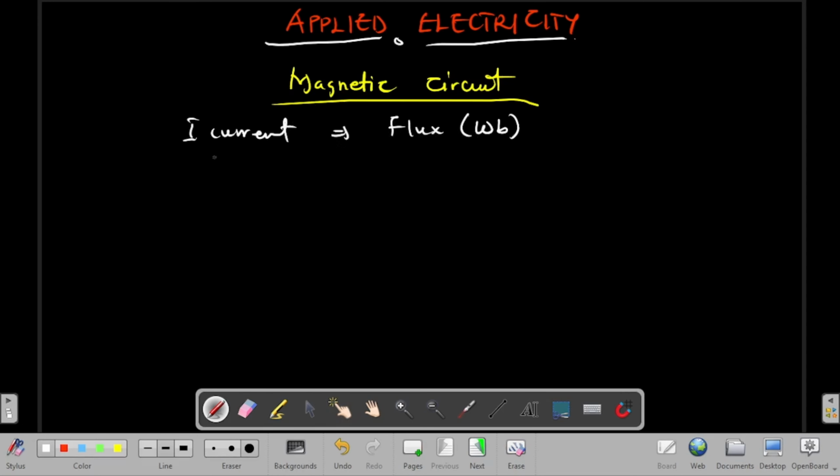The next one is what you call the MMF. I explained magnetomotive force. So here, this is like your voltage difference or your potential difference or what we know in our DC, right? So it's the same as the EMF that you know, right? Nothing changes. And you remember the formula, F is equal to N times I. So a supplied current times the number of turns gives us our total magnetomotive force.